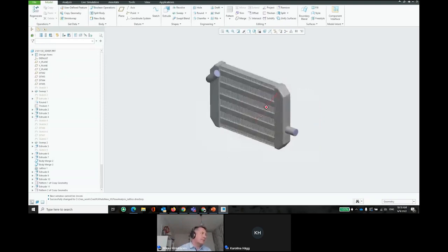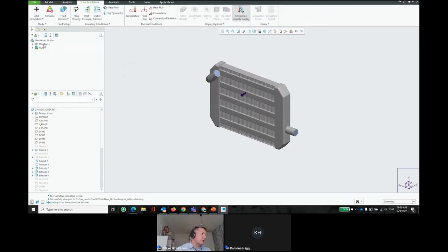So nothing specific in here, but then when you jump into the Creo Simulation Live environment, just click Live Simulation. You will see that there's one structural analysis, but there's one fluid analysis made in here. In here, you have this remove internal geometry button, which simply means that now we are taking into consideration that lattice geometry in there. Then we have a boundary condition, which says outlet pressure is 0 bar, and then you put 1 kilogram per second in, and then you have a general initial temperature in here. And basically everything is prepared for us to make it run. So we just click simulate.